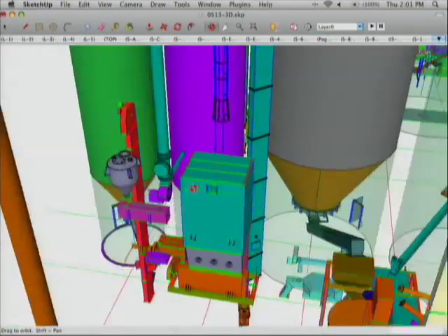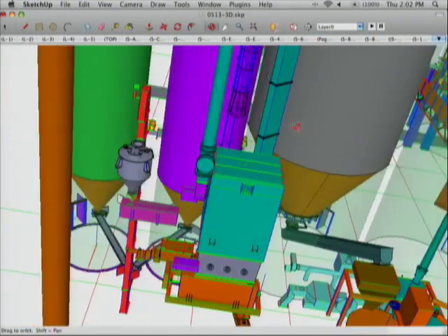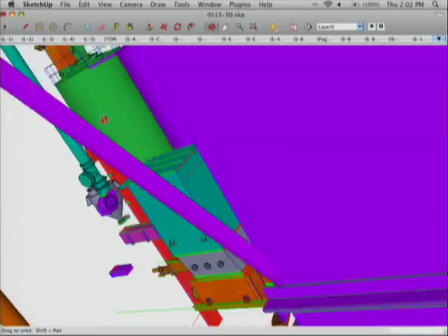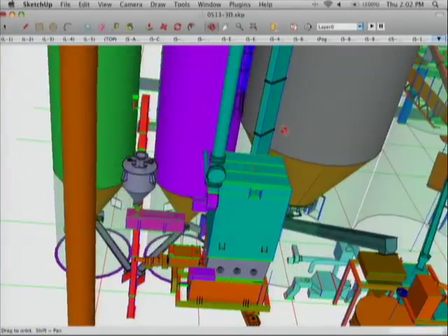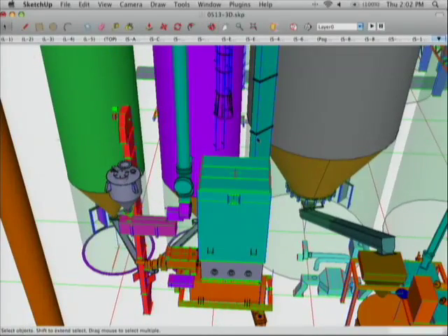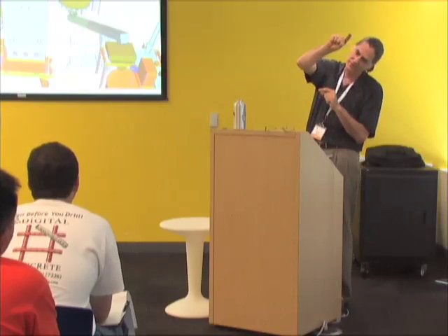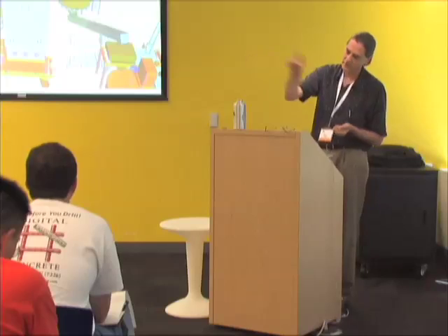Somebody asked me about demoing, so if I try to rotate this model over, it's like it's connected to the earth and gravity. If I hold down the alt key, I can tilt it. I usually find this helpful if somebody's asked me to model a house for them and they give me 4 plans and I bring them into a SketchUp model and I'm trying to do a component on each face and rotate around them, and I'm trying to rotate this huge piece of stuff and it won't turn. I can never get onto the side of it. Or a big plan like this, if I want to go around something, I can't do it.